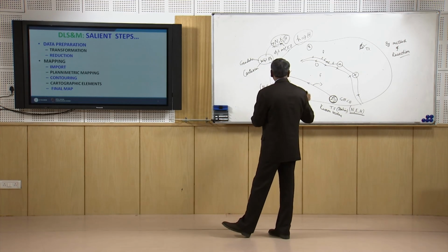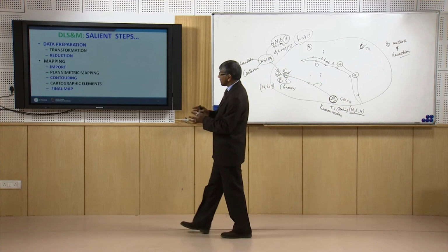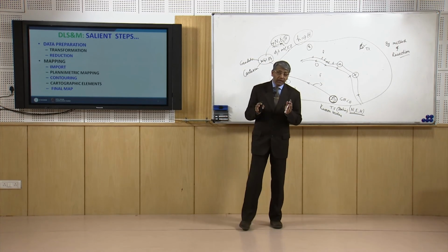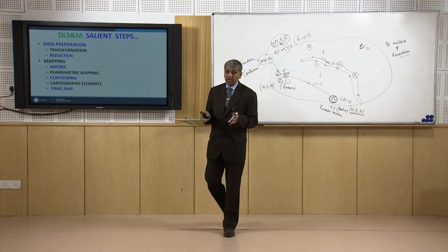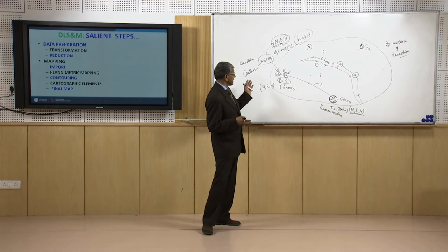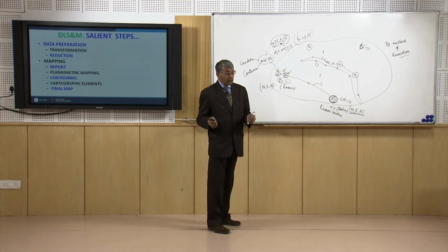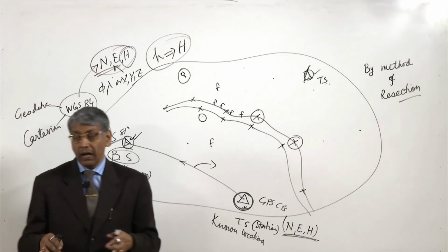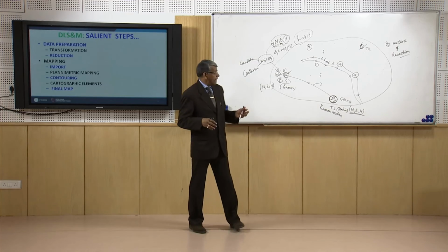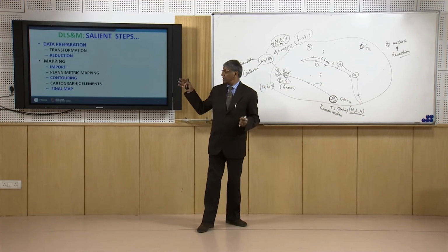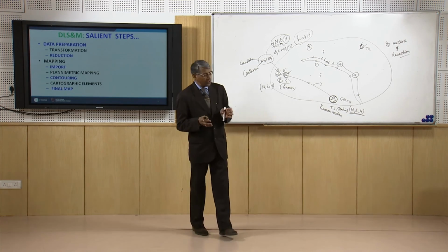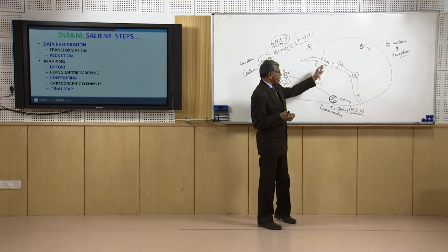After the planimetric map has been done, then we can go for contouring. For contouring we need all three coordinates: northing, easting and height. Northing and easting provide the planimetric position and height provides the height of the point, and then every software has its own techniques for interpolation of height between different points.